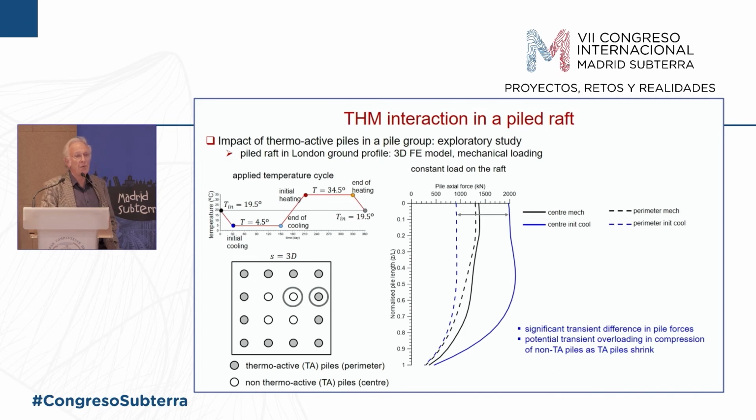So if you designed the reinforcing in your pile for this load, you might want to think about, well, maybe that's not the maximum load I should have designed it for. Plus, now you've got different loads in the central ones to the external ones, which is giving you bending moments in your raft, which you designed before such that you didn't have it.